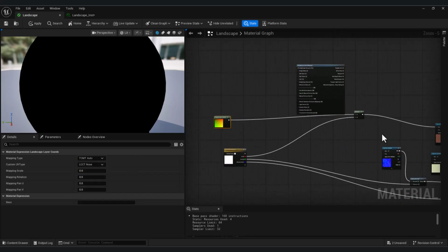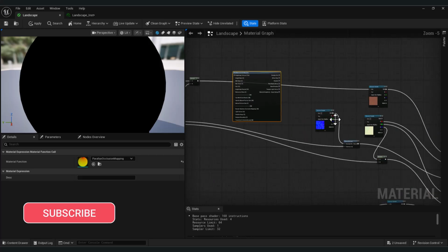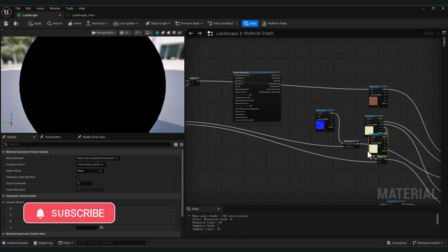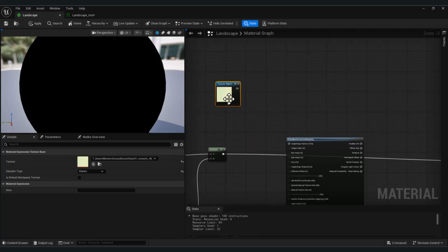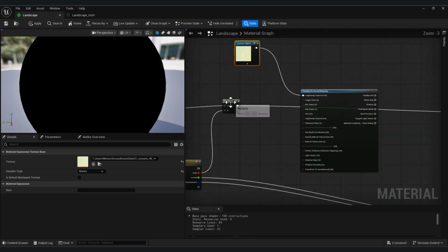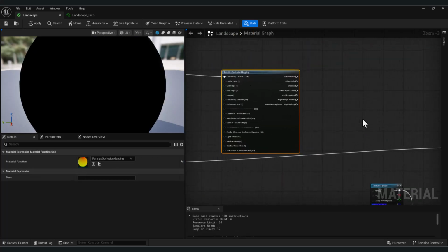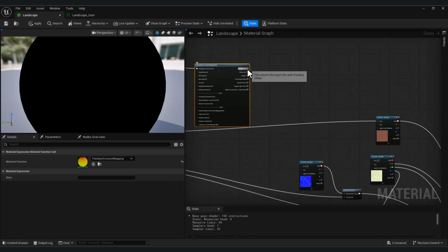First, we need our displacement texture. And here, we'll extract it from our other DP texture. Then, we make a copy of it, and to connect it to the POM node, we convert it into a standard texture. Now we need to connect the UV output to all of our textures. For the UV input, we'll use the same texture coordinate we multiplied earlier.